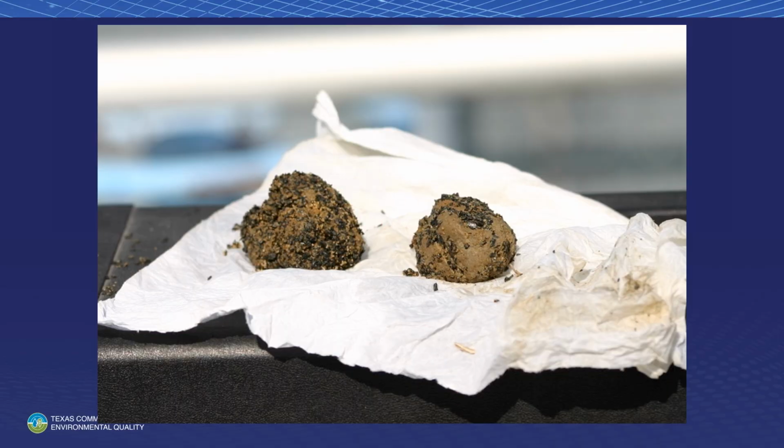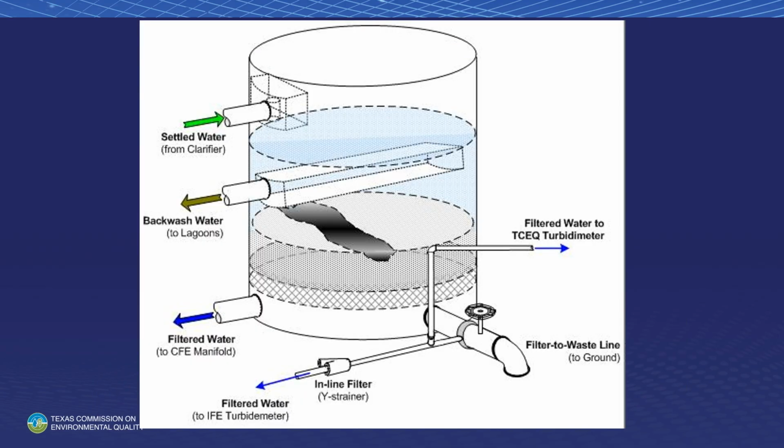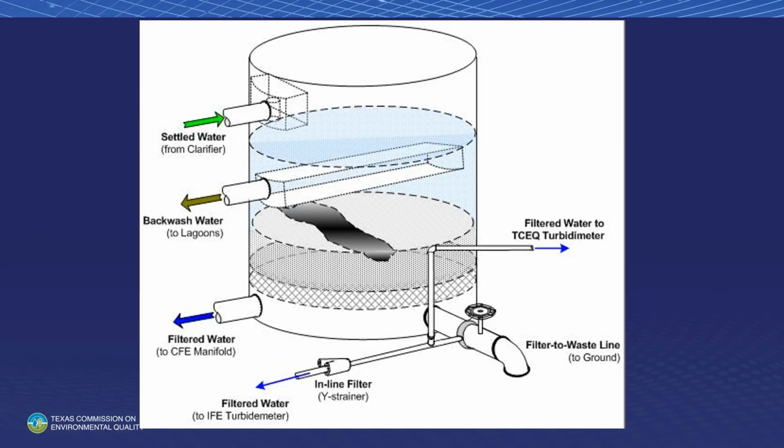The operators did 3 changes. The first change was to install brand new turbidimeters because they knew their turbidimeters were reading bad. They just knew it. And the turbidimeters continued to read bad. When we go out to provide technical assistance, we find out that not only did they put in new turbidimeters, they bought the European model of the turbidimeter, not the US model of the turbidimeter, and so they had to replace their new turbidimeters with other new turbidimeters. The turbidity would still spike.